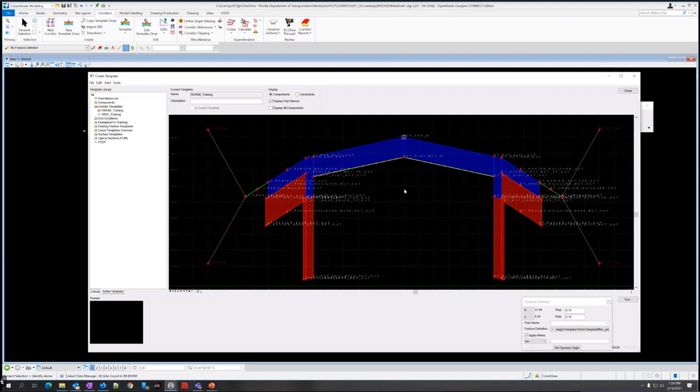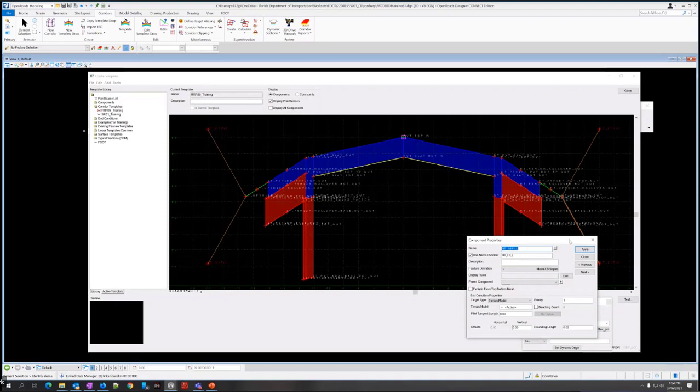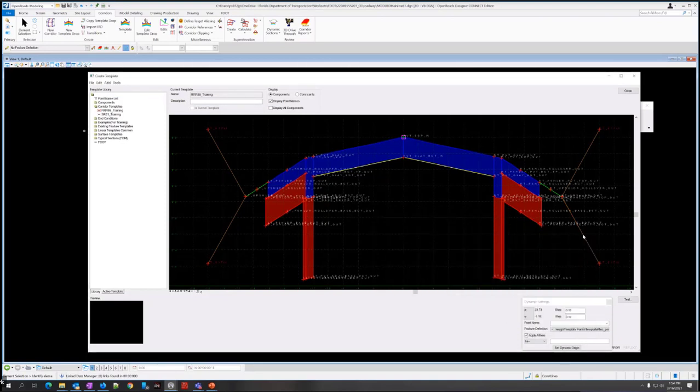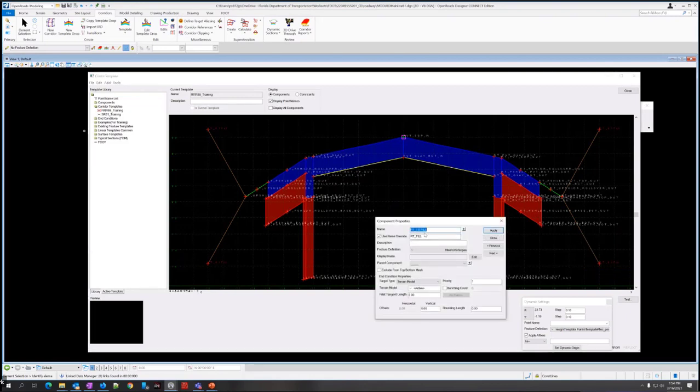All right, so now we need to change the fill components. If you double click on the points, it'll edit the points. If you double click on these lines or these shapes, these are the components, but usually it's the lines. You can't click on the fill on the side. You have to click on the line on the outside of a shape, or just this line here. So if I double click on it, it'll open the edit. I can also right click on it and choose edit component. But it seems like double clicking is quicker, so it's kind of second nature for me to double click.